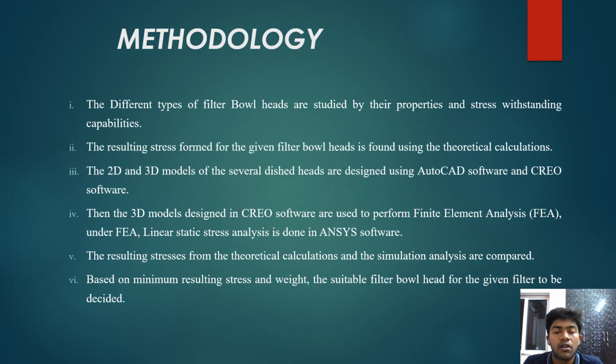Now here comes the methodology which is used for solving the problem. Different types of filter bowl heads are studied for their properties and stress withstanding capabilities. The resulting stresses for the given filter bowl heads are found using theoretical calculations, and then the 2D models and the 3D models of the several dish heads are obtained using the AutoCAD and the Creo software respectively. Now, the 3D models which are designed in the Creo software